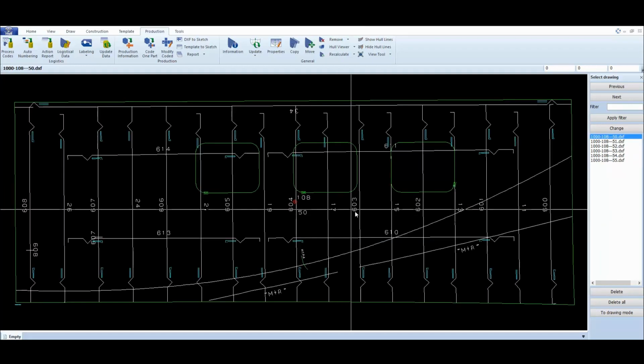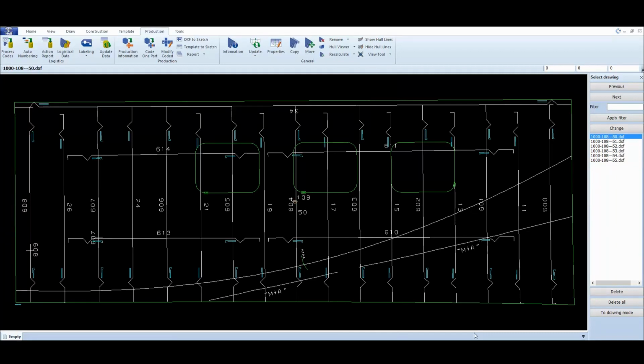Let's inspect one in more detail. These two lines here with the text MTR, this and this one, these are roller lines. The roller line is used to assist the folding of the shell plates, and that is why it is calculated when the shell plate is coded. The definition of the roller line is such that it can be useful to both supporting forming methods, to both cold forming and line heating. The text that you see here is also customizable.